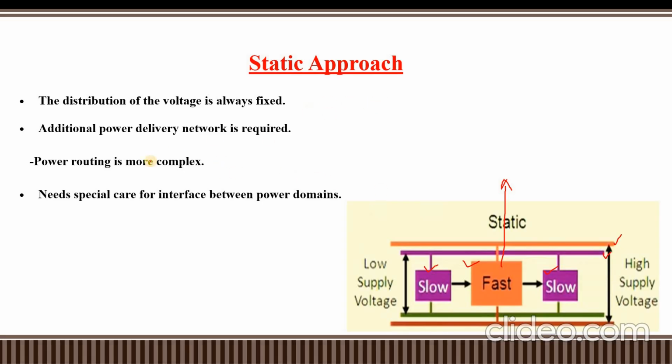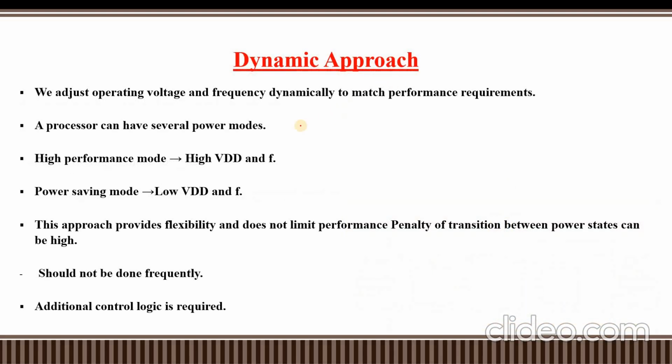But the major issue with the static approach is that power routing is complex. So we need to take special care for the interface between the power domains. It is one drawback of the static approach. Okay, see the dynamic approach. Nowadays modern processors have several modes. We can see, for example, a high performance mode.